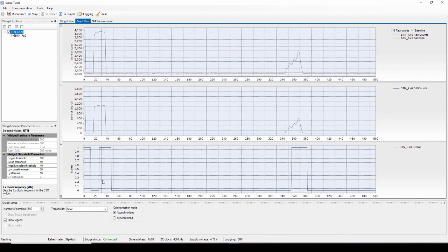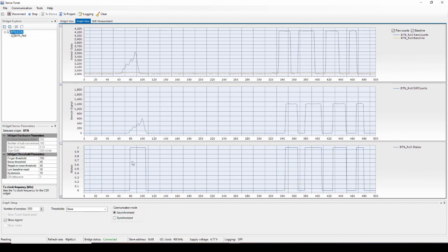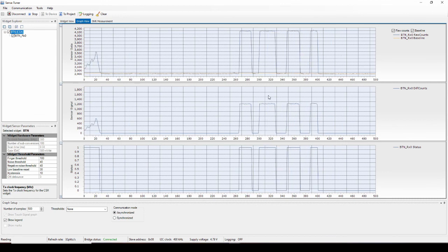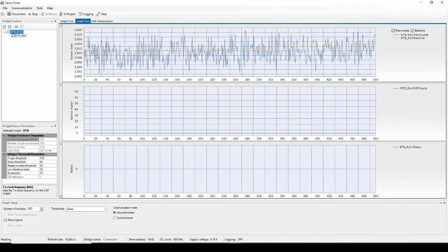And here at the bottom, you have basically the 0 and 1 value. So this is what you would use as a trigger signal, on and off, 1, 0, however you want to call it. So this gives you a nice way to graphically represent the reading that you have, and basically help with the tuning or the values that you're getting after you put in a different overlay or different materials on it.